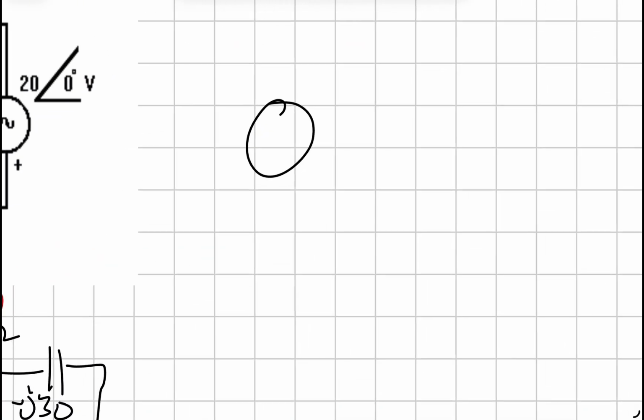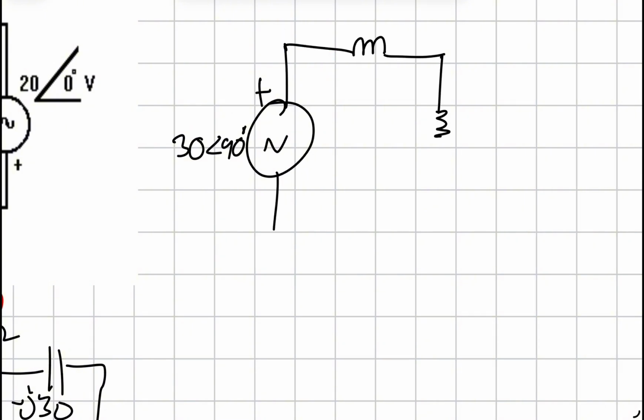The way I would do it is, this time it's a voltage source, so remember the rules. You just need to do the voltage rules, but then use Ohm's law after this. Make the circuit, 20 ohms. Alright, remember, when you're doing a Norton's current, you short the A and B now.